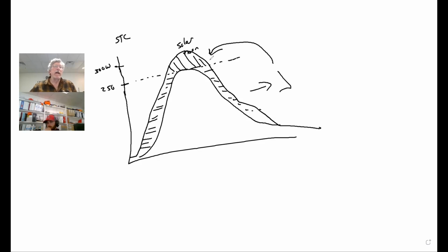So you'll still come out ahead having a bigger panel. The only downside of clipping is that you're paying for capacity of the panel that you might not use on some occasions. But the cost difference between panels and inverters has gotten to the place where economically a 1.2 ratio is good. That's typically what people are going to be designing to.